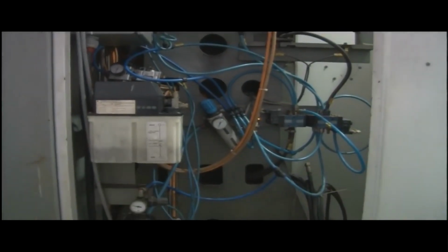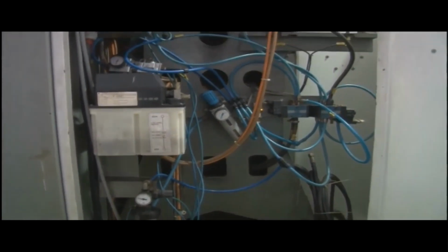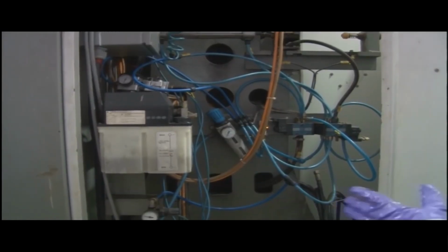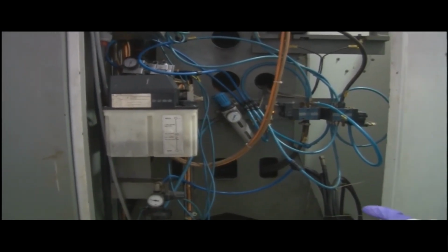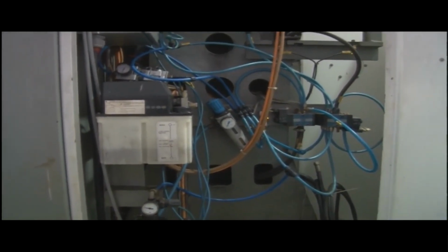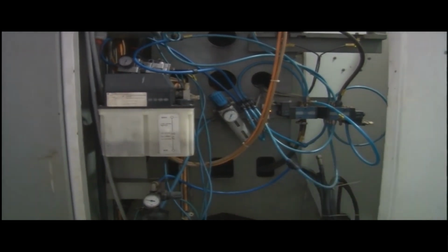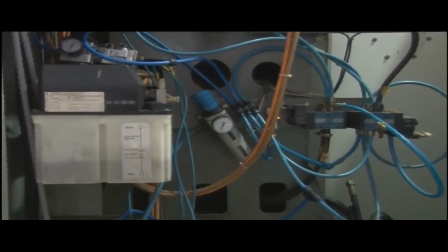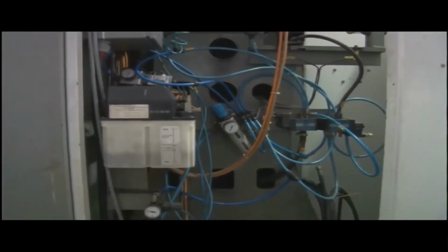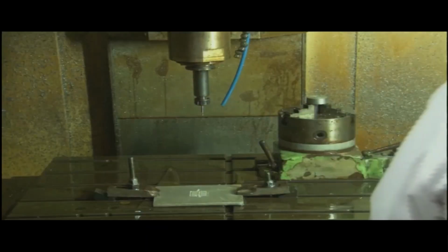This is also one of the supplies that goes to the spindle. With the help of the pneumatic system, with air only, the tool is held, as I just told before. So, this is all the pneumatic system that is there. So many LVDTs, solenoid valves, pipes and pressure gauges are there, all integrated in the machining system itself. Normally the machine needs 6 bar pressure. You can see it is a little less than 6, so it is close to 6 bar. This is the pressure needed by this specific machine to work.